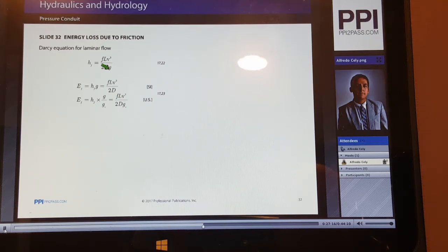The purpose of estimating the friction factor is so that we can calculate the head loss in pipes. The friction factor may need to be recalculated after finding the head loss in the pipe. The head loss can be added into the Bernoulli equation to calculate how the friction is impacting the velocity, pressure, or elevation of a system. This is very important in pipe network design because the friction in the pipe can impact the total energy needed to get the fluid from the inlet to the various outlets.